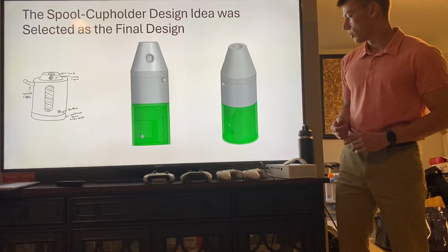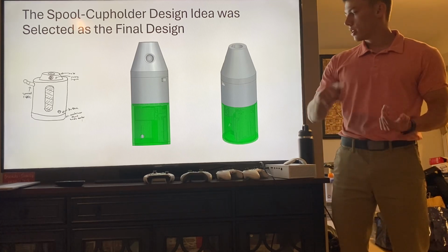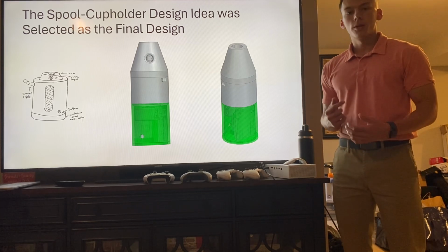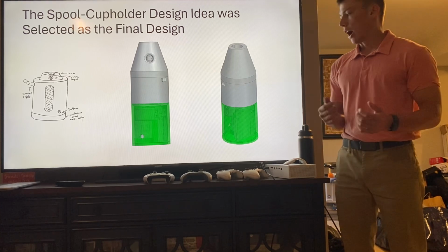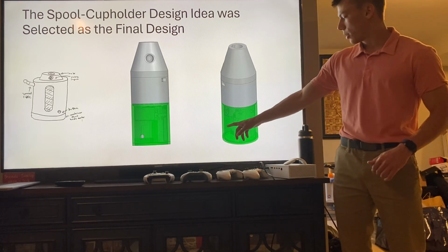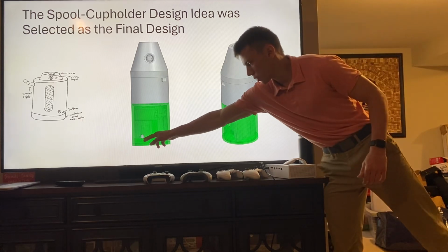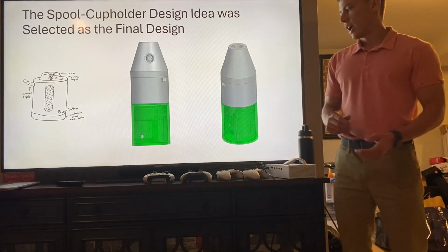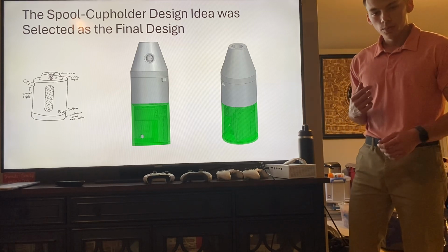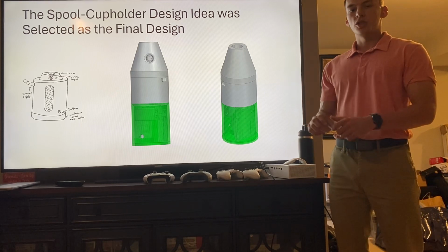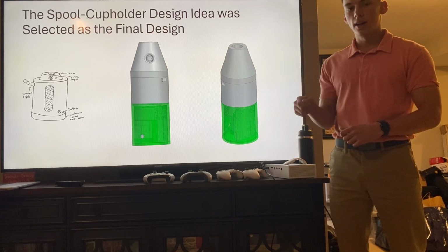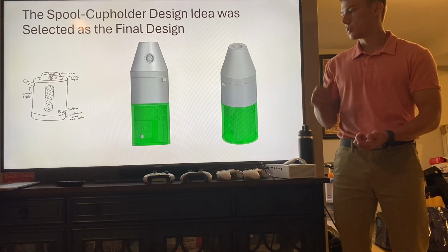The lower shell then contains the servo, the Arduino, the battery, the button, and the breadboard in which the servo will be operated, and the user will be able to press a button which will go into this hole or this hole, which is the same hole, just two different angles. And that will activate the servo to wind it up. The bike lock cable is able just to be pulled out and inserted, and it automatically locks. And then you need a key to unlock, and then you can wind it back up using the button.